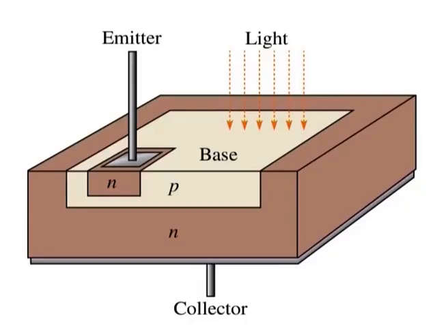Since the actual photo generation of base current occurs in the collector-base region, the larger the physical area of this region, the more base current is generated. Thus, a typical phototransistor is designed to offer a large area to the incident light, as this simplified structural diagram indicates. A phototransistor can be either a 2-lead or a 3-lead device.